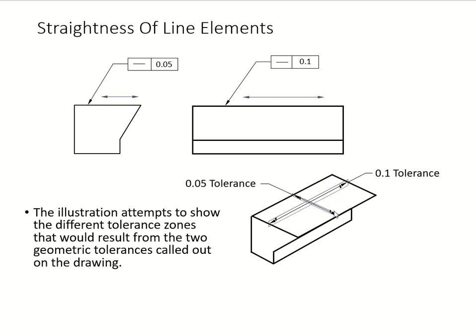This is a 0.05 tolerance for your front view, and this one is your right side view, which is your 0.1 tolerance. Front view is looking at these edges right here, and the right side view is this. For the same surface, you have two different dimensions. Here, you would call that a width, and this one is your depth.